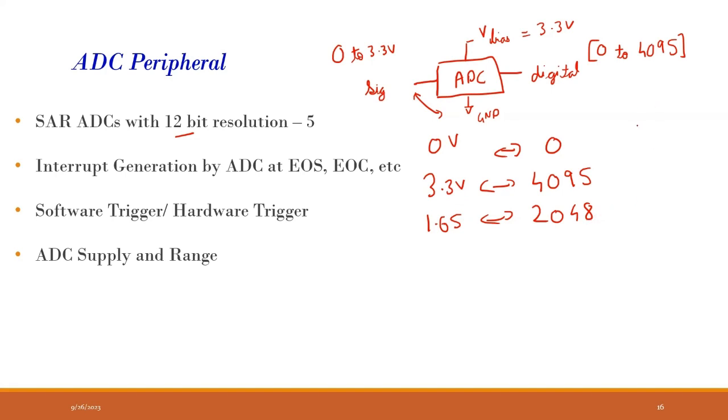So there is an option known as gain compensation. I can do gain compensation. Whatever value it will generate, 4095, the ADC will convert that into some particular value based on some formula which is available to us. I have written it in such a way that if I give 3.3 volt, it should generate 3300, meaning it is converting from volt to millivolt. So if I give 1.65, it should show me 1650. Is there any query in this?